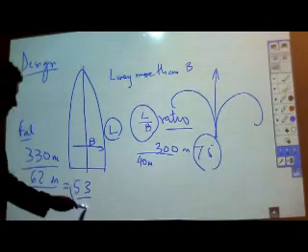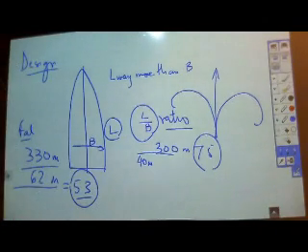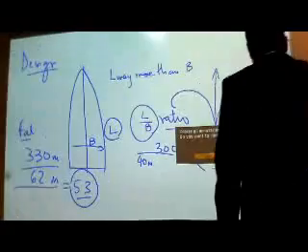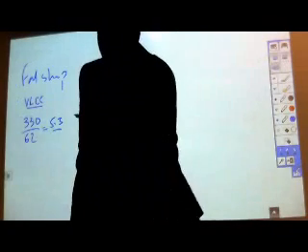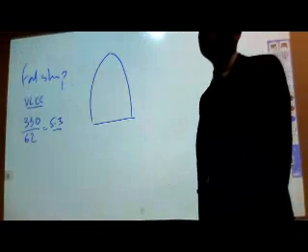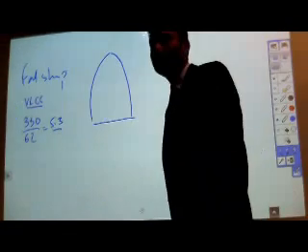Well, you can't talk much about ships that lie somewhere in the middle, can you? It is always good to draw conclusions from extremities, and then you can apply them to other kinds of ships. What is this going to affect in the maneuverability of this ship? Well, let's look into it. Fat ship. Just giving an example, a VLCC. Length 330 meters, beam 62, and you said it is 5.3. The ratio is 5.3. Do you think this ship is going to be directionally stable? Something like this, it is not going to be directionally stable, it's very fat.